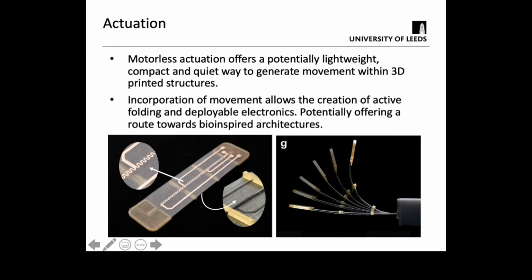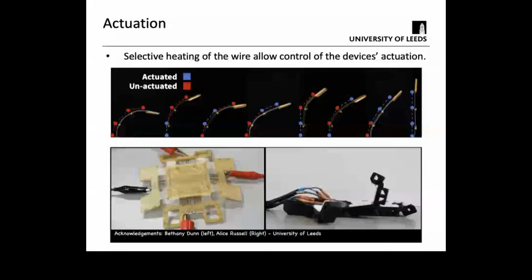The nice thing about the approach here is most individuals, when they use a shape memory alloy like nitinol, muscle wire as it's commonly called, directly attach the current to the wire. So the Joule heating directly goes through that wire, and it does not enable any selectivity. Because we printed these discrete elements, it allows us to do some forms of selective actuation. This slide shows you how, depending on what segments we turned on or off, determined the movement of that part.